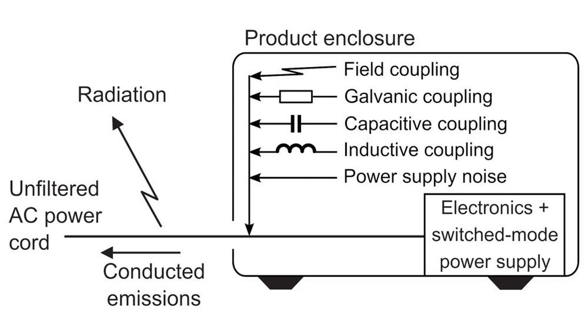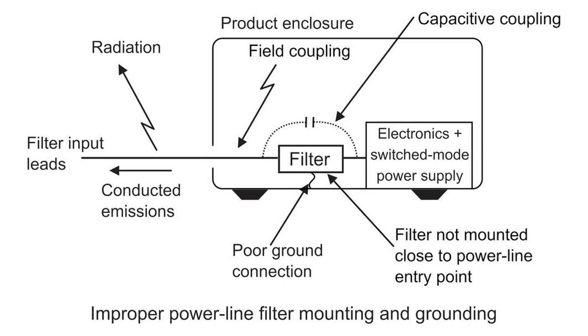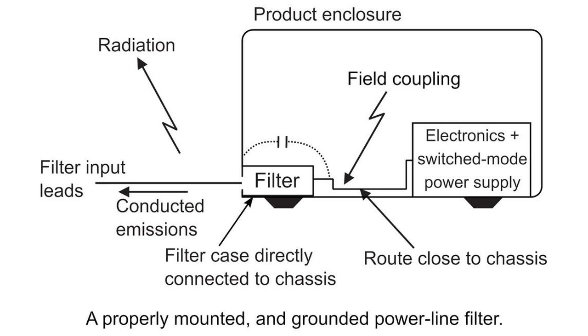Power supply filters. Virtually no electronic products today can comply with conducted emissions regulations without the aid of a power supply filter. Power supply filters are inserted where the power cord exits a device, thus they prevent conducted emissions currents from exiting the device. An important aspect of power supply filters is the fact that they must reduce both the common and differential mode currents from the device they are filtering in order to satisfy conducted emissions regulations.